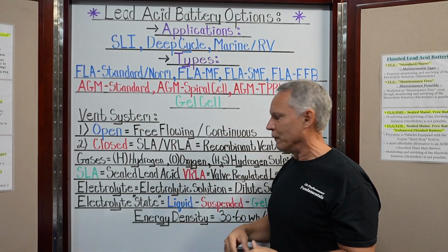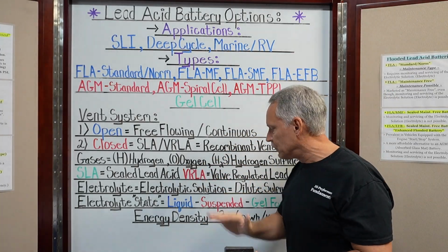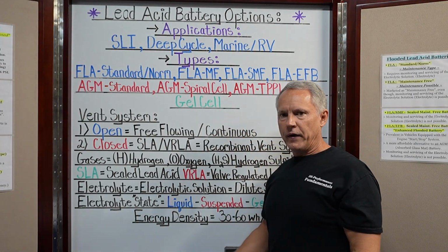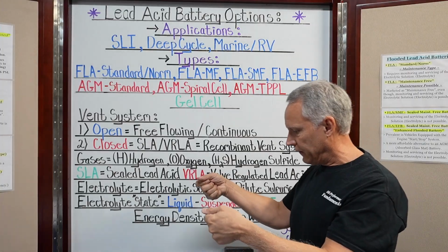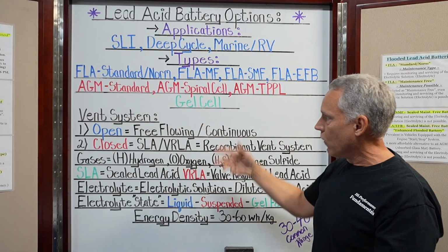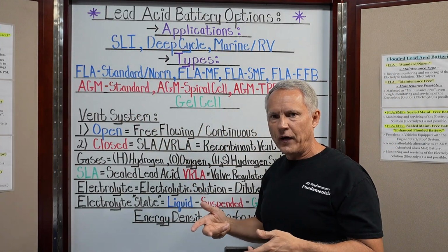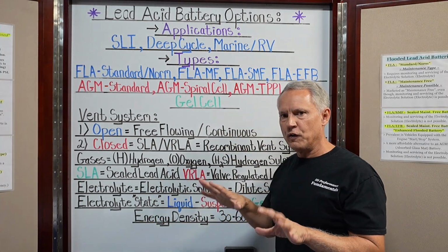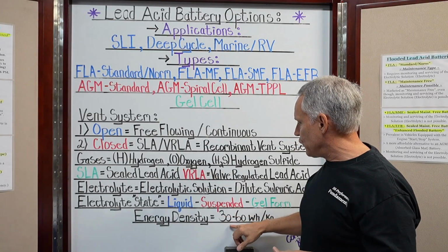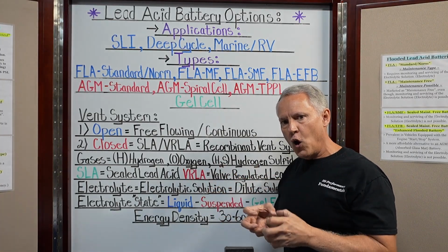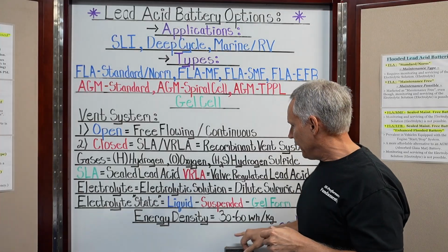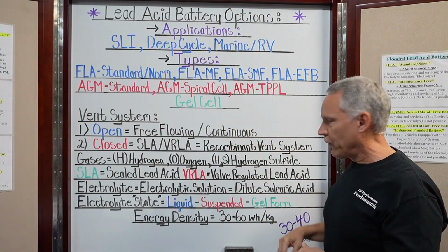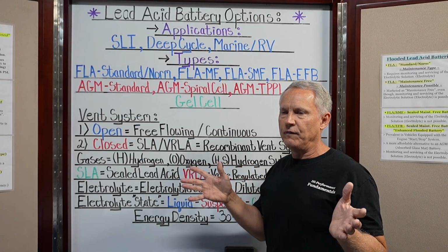Let's just say this and we'll cut it short. If you physically weigh a battery, and you take a lead acid, say a standard AGM, and a lithium iron, lithium ferrophosphate or lithium iron phosphate, and you weigh them side by side, let's say they both have the same amount of energy. Since the energy density of a lead acid battery is much lower than that of a lithium-based battery, this battery, let's say, just come up with a number, ends up weighing 22 kilograms, or roughly 48, 49 pounds.